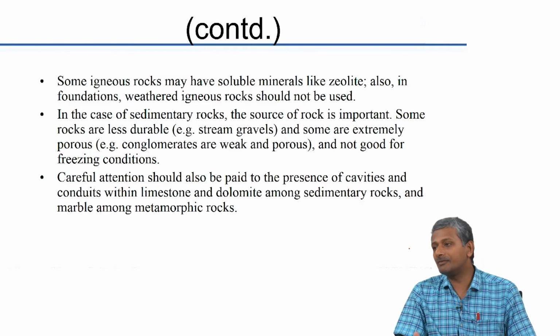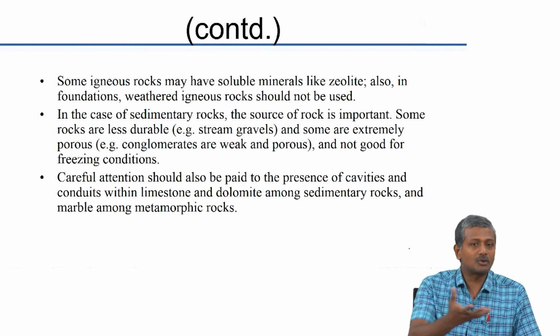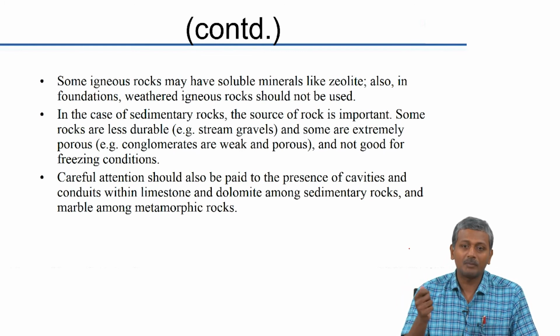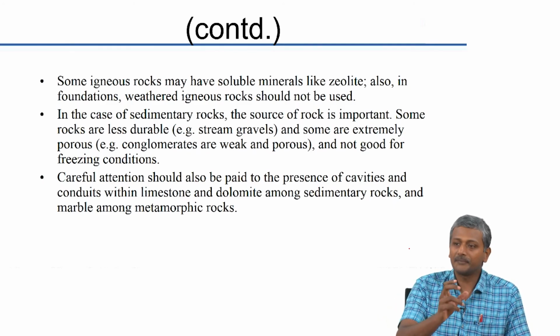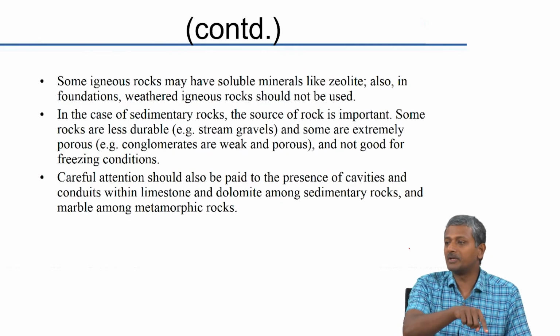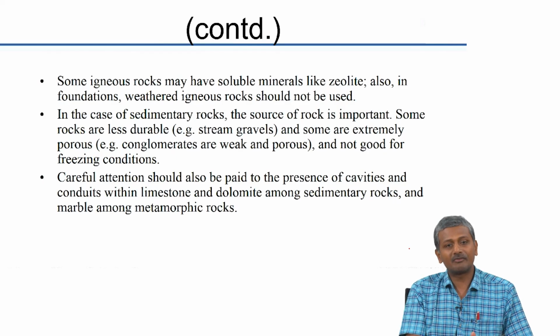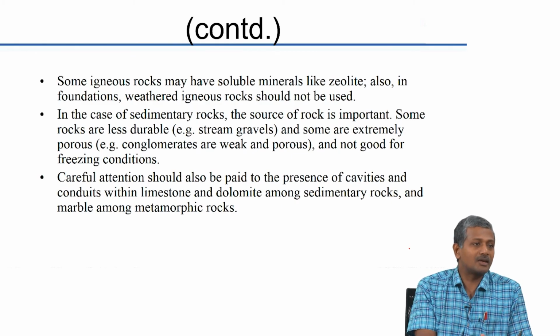Now, interestingly, the way that the aggregate is screened from a riverbed is quite interesting. You have to collect a sample of nearly 200 pieces of the aggregate. You have to go through each one megascopically. That means you have to evaluate each aggregate piece visually, and then of course do the kind of mineral test that we already talked about previously. You need to then fraction it into the components, that is, regular density. That means what do you expect the density of aggregate to be typically? About 2.7 to 2.8, around that would be the density of most aggregate, right.